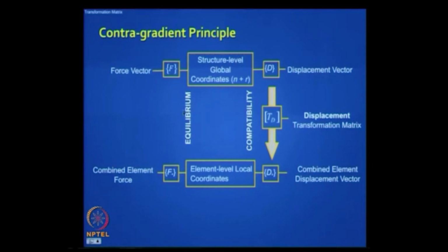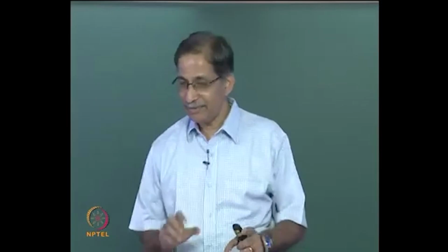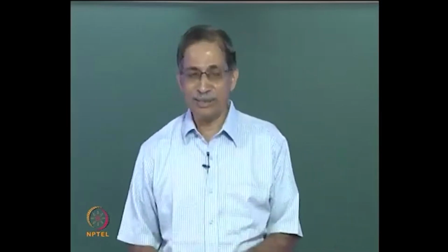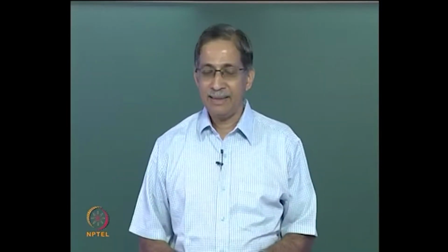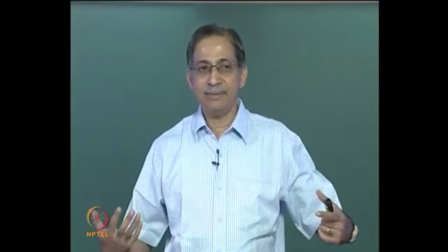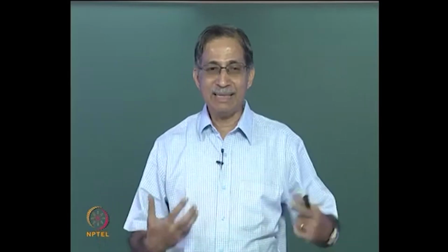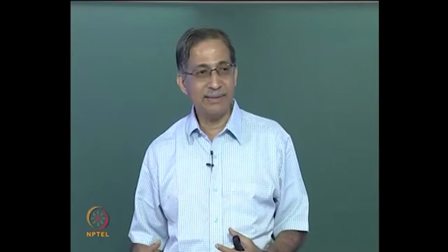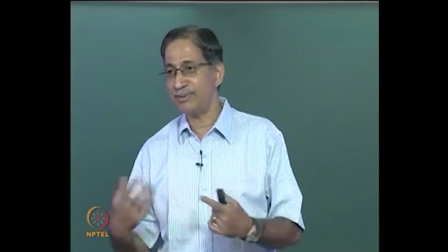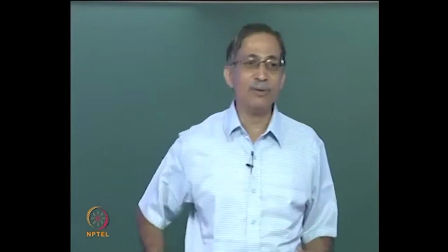Do you think this relationship is linked to the TD matrix? Can we prove that relationship? How do you prove that relationship? This is a very important concept. How do you relate the element level forces to the structure level forces in the way we related the element level displacements to the structure level displacements? What principle will you use?